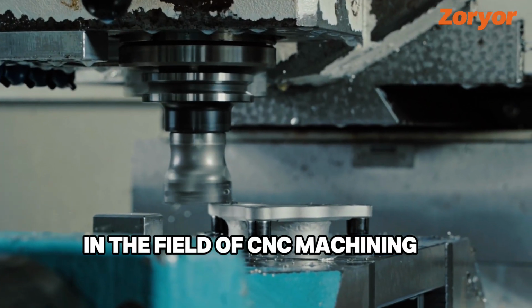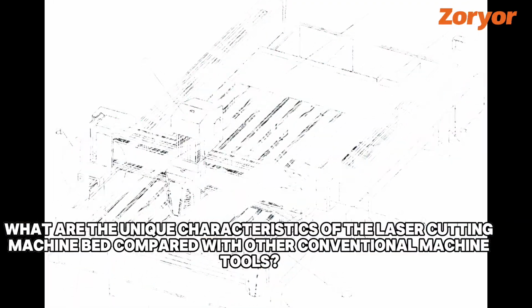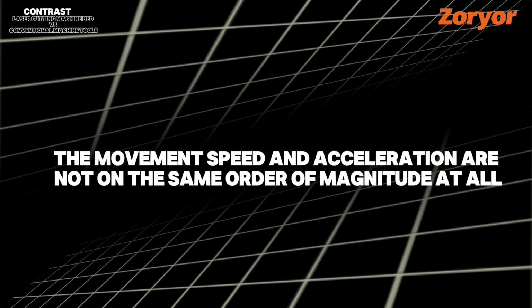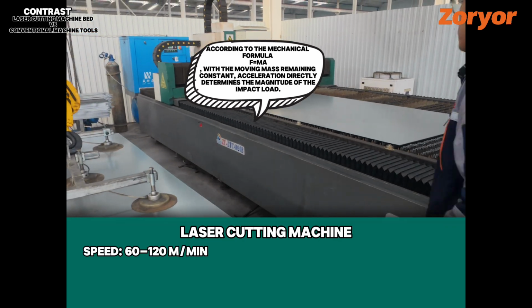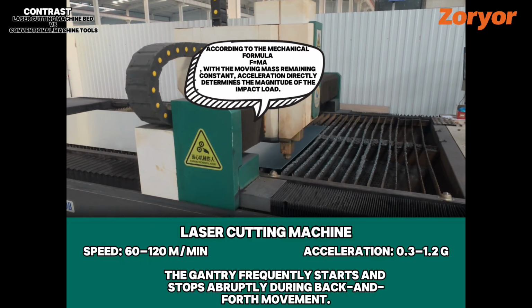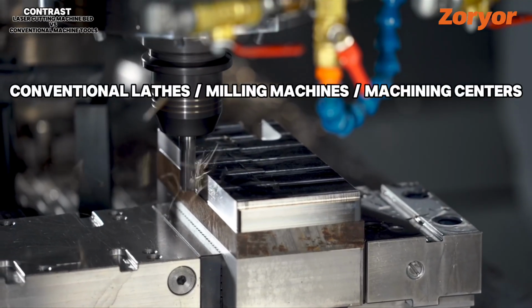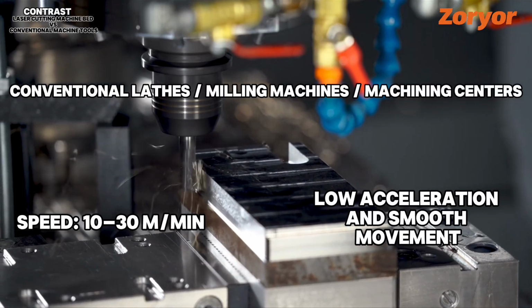In the field of CNC machining, what are the unique characteristics of the laser cutting machine bed compared with other conventional machine tools? First of all, the movement speed and acceleration are not on the same order of magnitude at all. Laser cutting machine speed 60 to 100 m/min, acceleration 0.3-1 g. The gantry frequently starts and stops abruptly during back and forth movement. Conventional lathes, milling machines, machining centers: speed 10-30 m/min, low acceleration and smooth movement.